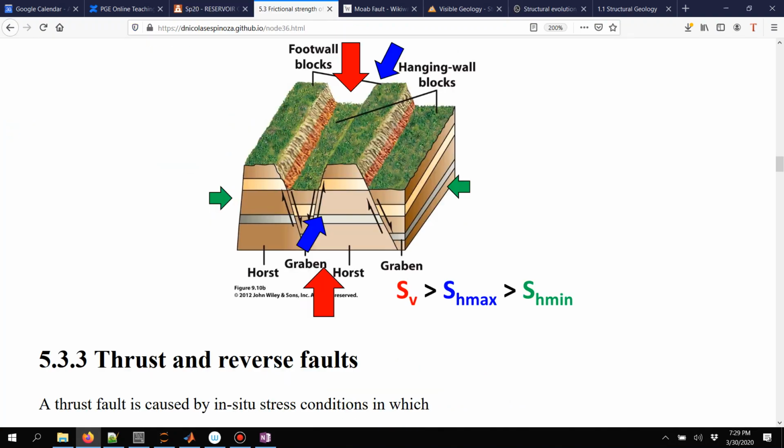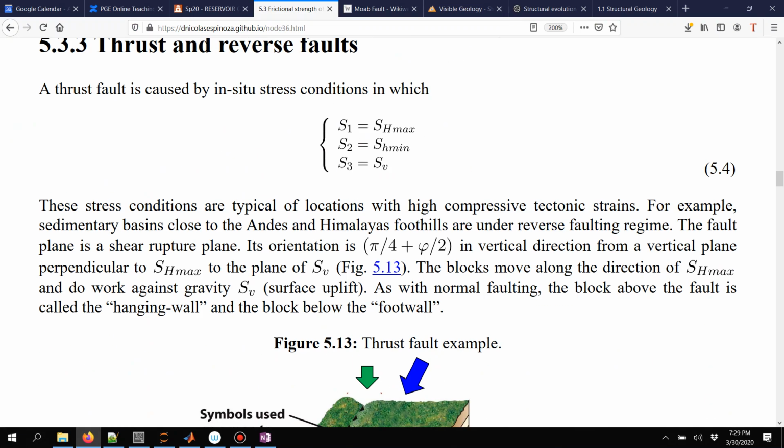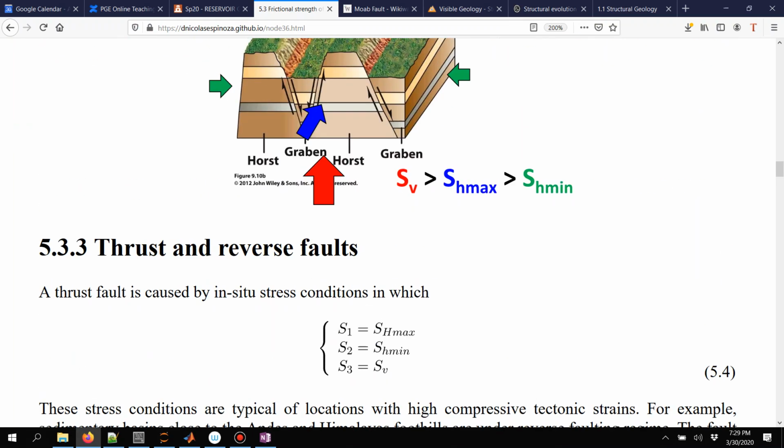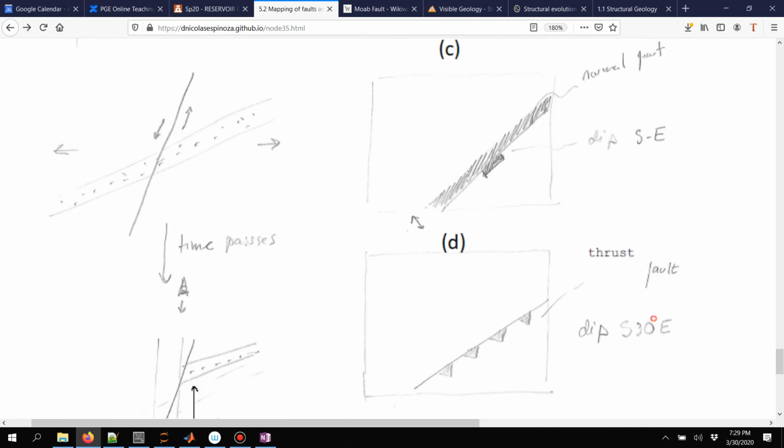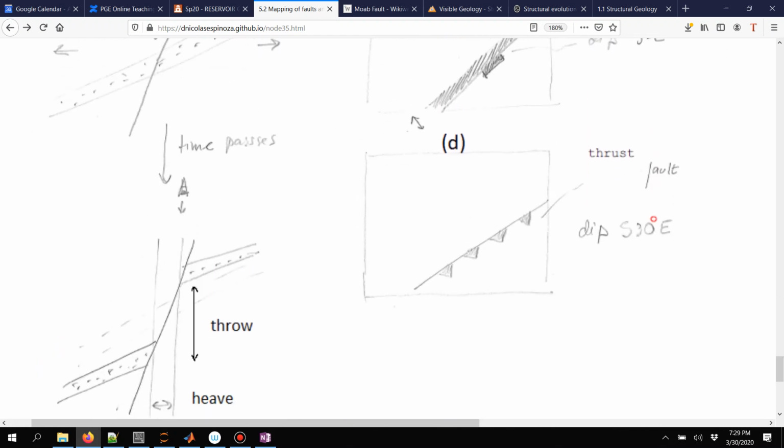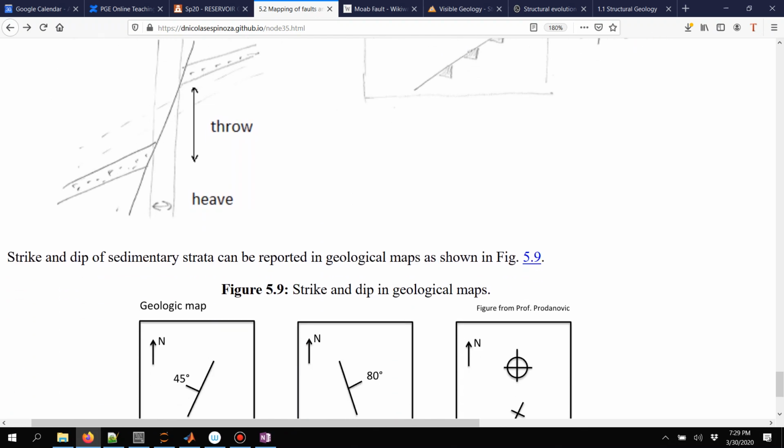All right, one more thing over here now related to geological maps is that with these geological maps you can also make schematics of a thrust fault. In a thrust fault, opposite to what happens with a normal fault, you will see two sections when you look from the top overlapping on each other, and the geological symbol that you use are these triangles, where the side of the triangles also tells you in which direction this thrust fault is dipping.